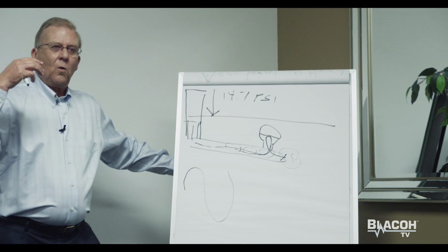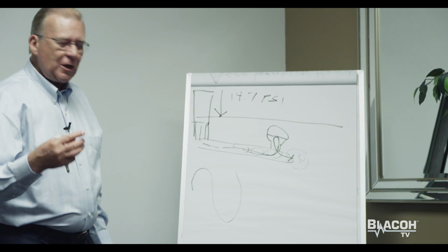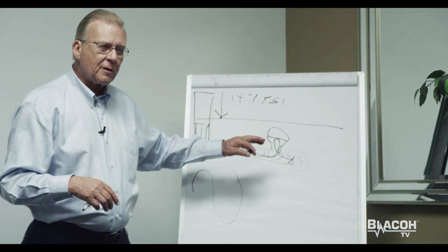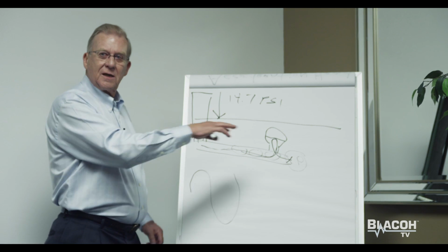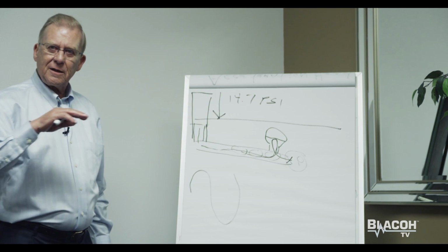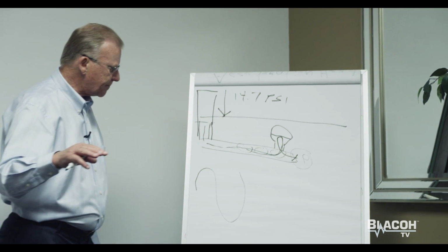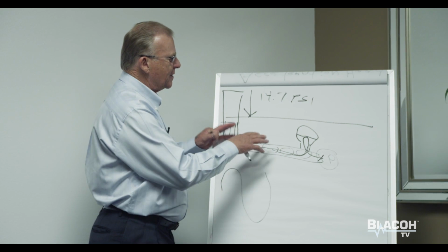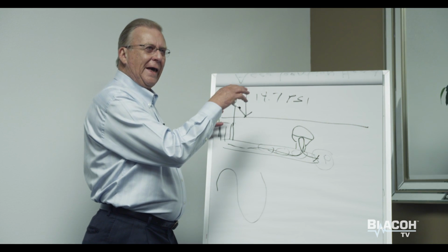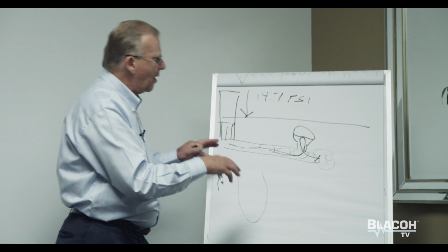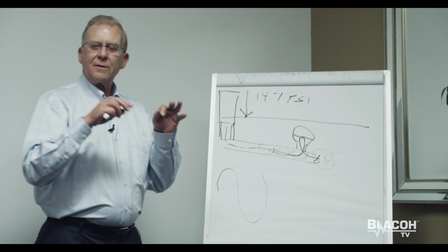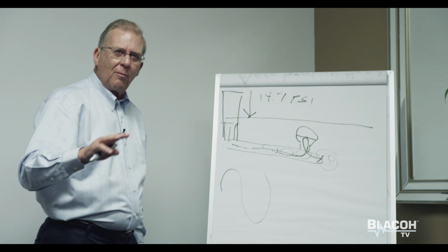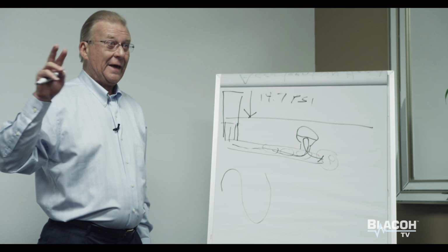Now, we have effectively changed this acceleration head, whether it's loss or pressure, into steady state flow at a constant pressure and a constant energy requirement. Okay? So the whole point is to change this reciprocating flow, and it's either gain or loss from acceleration head, into a constant steady state flow, so that we eliminate the problems created by this acceleration head.